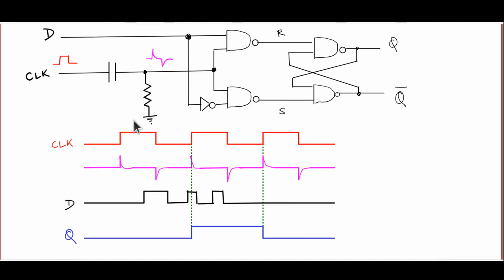Here we have shown a square wave clock signal which goes up and down and stays up for quite some time, down for quite some time. But once it goes to the CR, this is what the D flip-flop actually sees. Sharp positive spikes whenever the clock signal goes up, sharp negative spikes whenever the clock signal goes down, but the negative spikes, just like the zero voltages, are treated as low by the circuit.